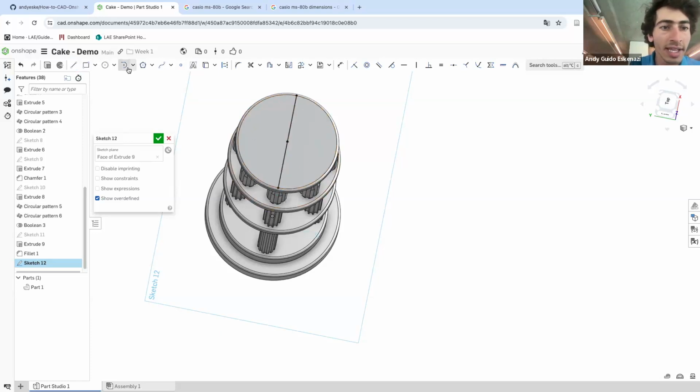Very good. And then I'll do here where it says 3-point arc. So I click on the arc, I do this point, I click on that point, I click escape, and then as we saw before, I can do concentric, right? So I can click on this and that, and you see how it comes there. So now everything became black.